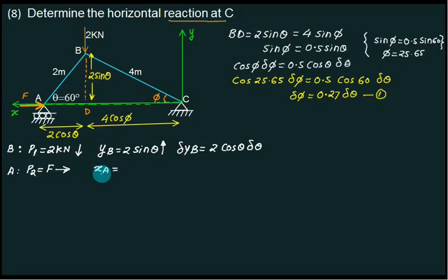The x at point A is this total distance. Does it consist of two parts? One is 2 cos theta, the other is 4 cos phi. This total distance is the x coordinate of point A. Is it leftward? What is the direction of x? Leftward, so use the same direction. We are in the second quadrant. So this one is delta xA. The derivative of this one is minus 2 sine theta del theta.